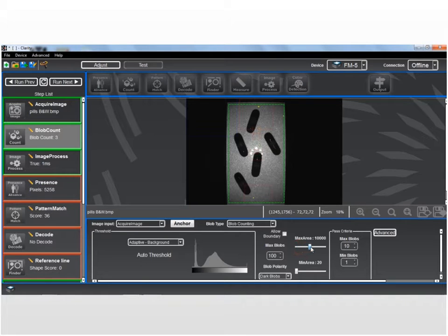What I can do is use these sliders to set a region of interest for the amount of area that the objects I'm looking for will cover in pixels. So really, how big are the objects I want to see? You can see I moved those up higher, and right away I recognize all these pills. I'm recognizing from about 30,000 pixels to about 72,000 pixels of coverage for those objects.